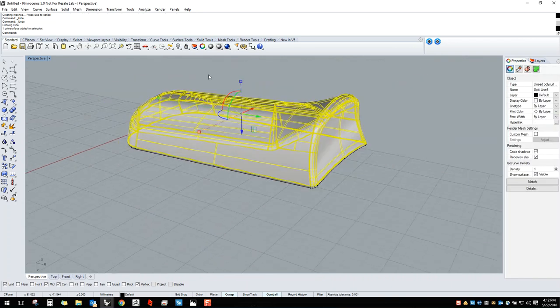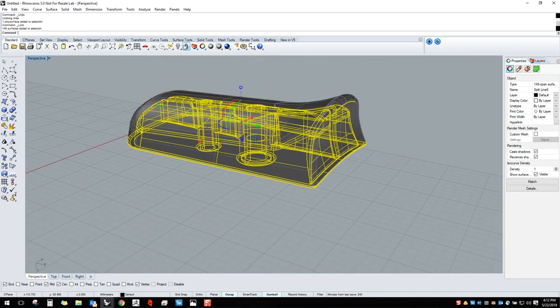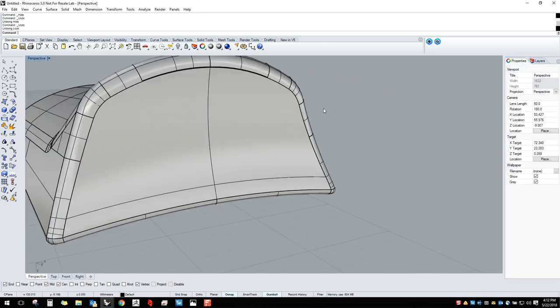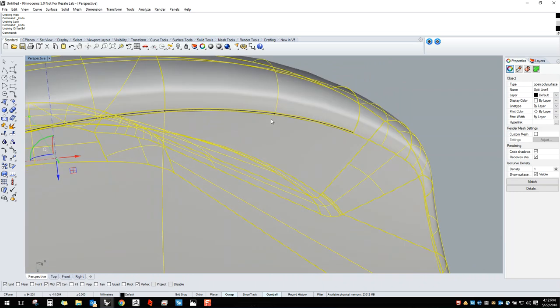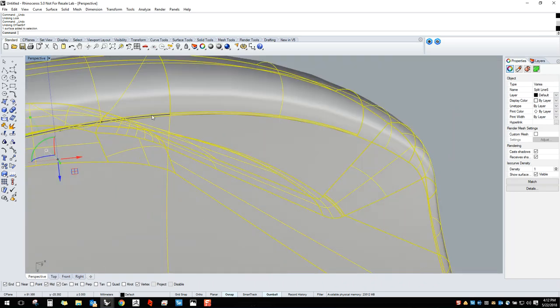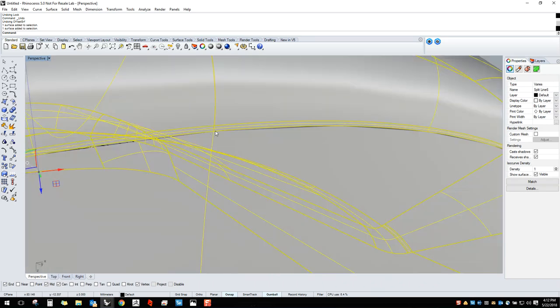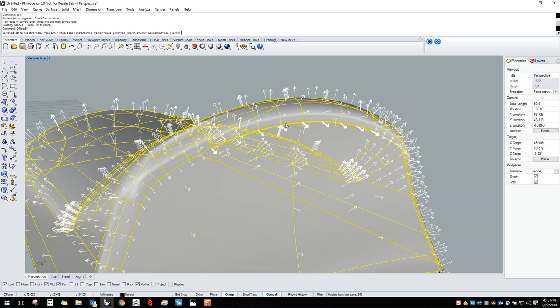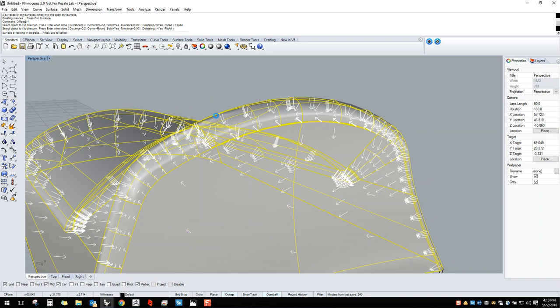And then let me hide everything else. I forgot a little part here. Let me add that back in real quick. This part has a lot of tiny little pieces on it. So join, offset surface, inwards, because I'm not trying to change the exterior diameter or the exterior profile of the part. Everything goes to the inside.